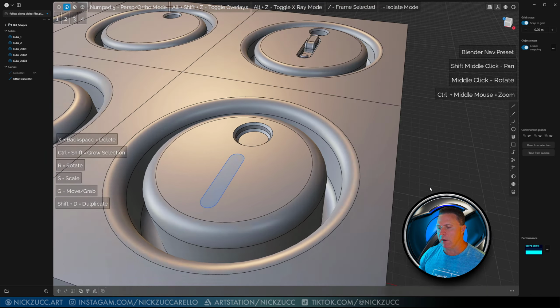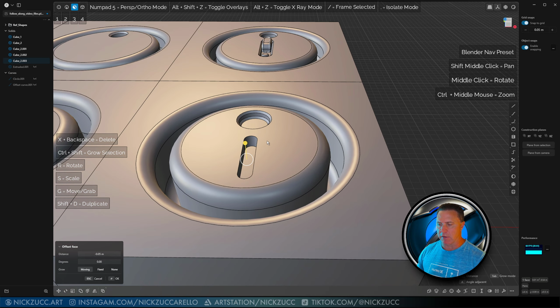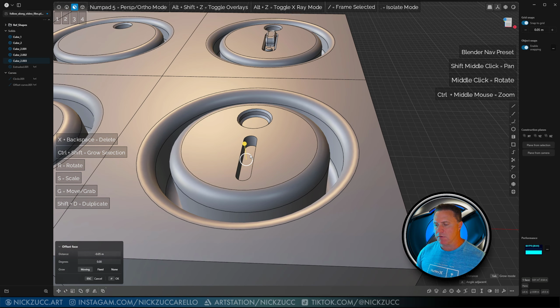as like maybe if we looked at an extrude. This is offset face, but we are just pushing this face directly down through here like that. Now, if I tried to do this, I'm going to turn off the grid snapping, and if I do this degree function, it looks like it's probably going to fail on me like that. So if I select this and I tap E to do an extrude, and I extrude down, and then I do this